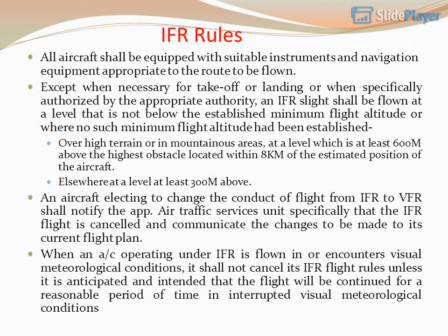IFR rules. All aircraft shall be equipped with suitable instruments and navigation equipment appropriate to the route to be flown. Except when necessary for takeoff or landing or when specifically authorized by the appropriate authority, an IFR flight shall be flown at a level that is not below the established minimum flight altitude or, where no such minimum flight altitude has been established, over high terrain or in mountainous areas, at a level which is at least 600 m above the highest obstacle located within 8 km of the estimated position of the aircraft. Elsewhere, at a level at least 300 m above.